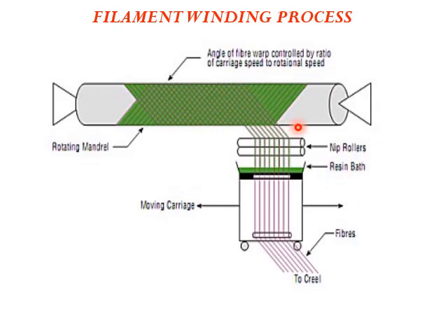So once the winding of these fibers is done, it is transferred to the curing furnace, where it is heated to a particular temperature to get the required compactness. Then we get the finished product.